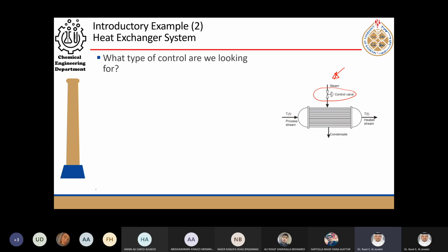Usually, this is also something that you need to know, that the steam cycle is a closed cycle. What does closed cycle mean? This steam is converted into condensate. It goes back to a plant where it will be transformed again to saturated steam through boiling, and then returned back. Why? Because the quality of water I use in a steam cycle is of a higher standard than the normal water, or the normal potable water I use everywhere else. It has been treated in such a way to make the system immune against corrosion.